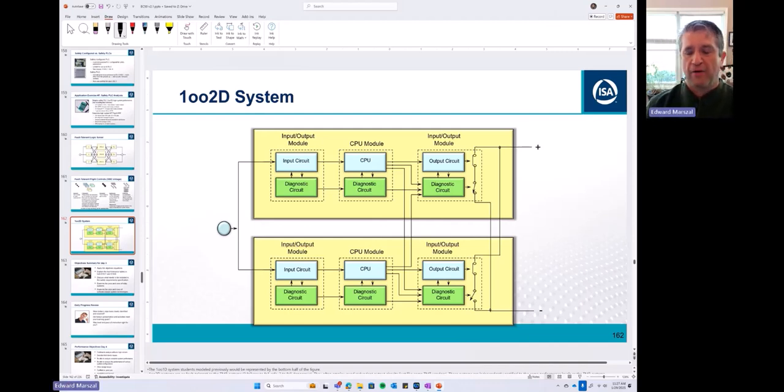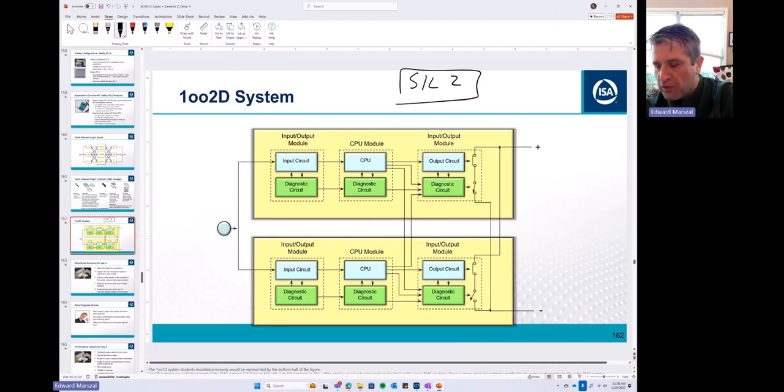Okay, now where is the middle ground? The middle ground is going to sit in this SIL 2 certification. So when you get a PLC with a SIL 2 certification, read through the safety manual, because they might end up giving you instructions for how to build that watchdog timer system that I just presented to you.